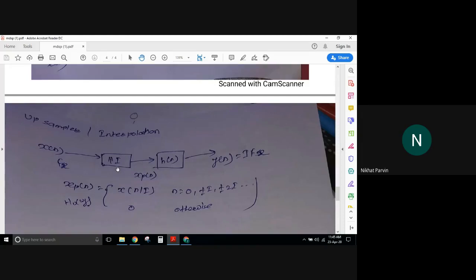You don't want images to go on coming one after the other. We want only a certain pass band of images to get passed, and the rest should be rejected. So to avoid that, we are using the low pass filter at the output of your interpolation. Here the input to the interpolation is your x of n, which is sampled at fx equals 1 by dx. Then it will get I of fx, which is passed through h of n, a low pass filter.